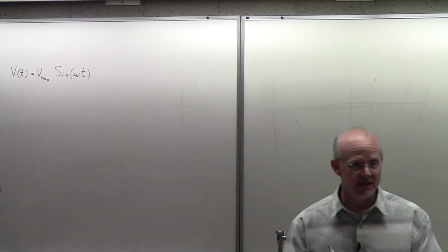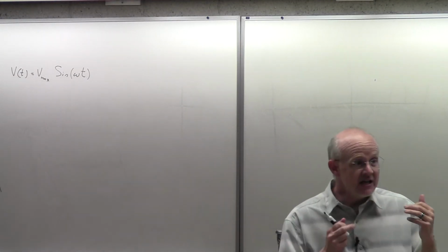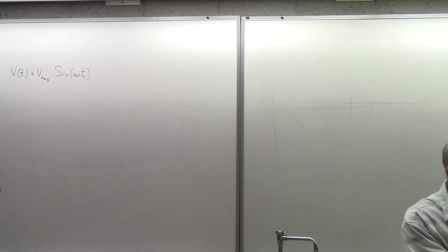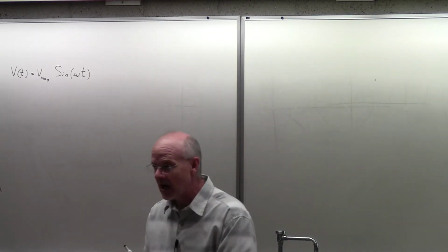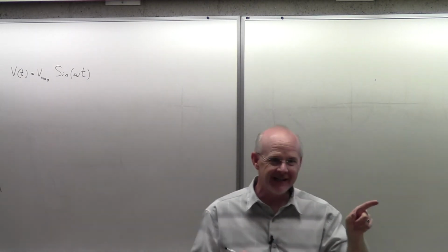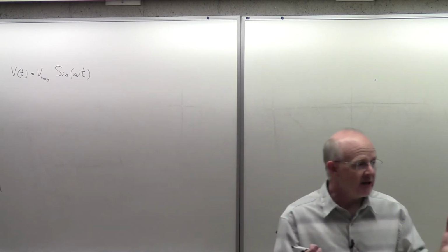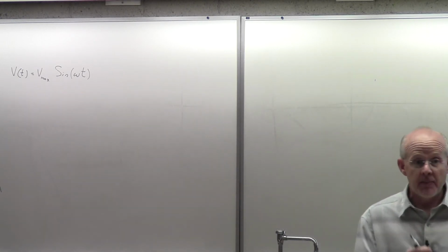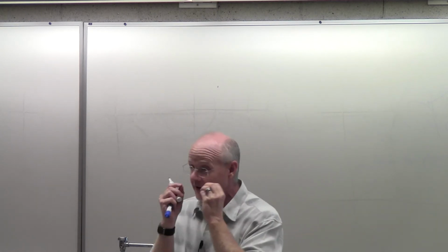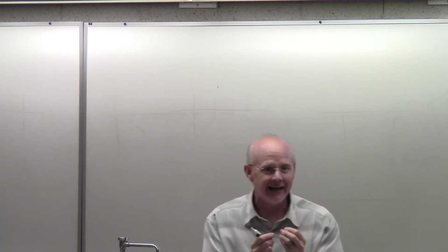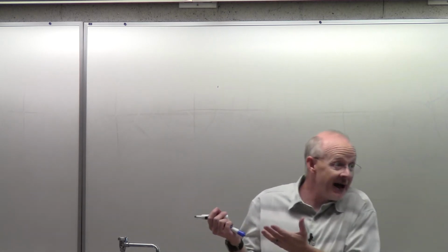That's just the opposite of the inductor, right? For the inductor, because of Faraday's law, I expected very little current at high frequencies. But for the capacitor, I expect very little current at low frequencies. On the high frequencies, I have very little to almost no opposition, because until the charge actually gets a chance to build up, there's no electric field stopping the current from building up. Let's see what the math comes out to.